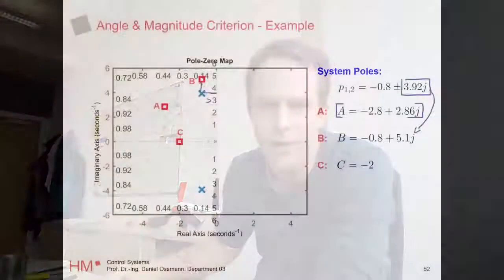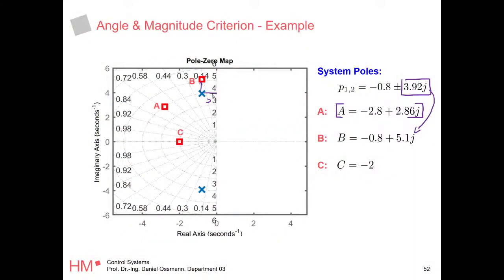At this point, you probably realize that only one of these points, namely B, is on our root locus curve, right? So what you could do is plot the root locus curve for our PD2 system at this stage, and you know that the root locus curve looks like this, right? Same as before. We've covered it a couple of times now.